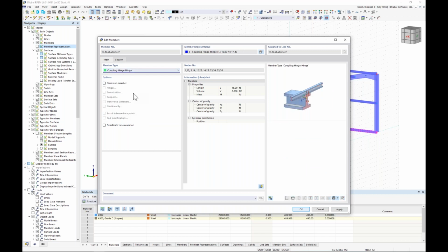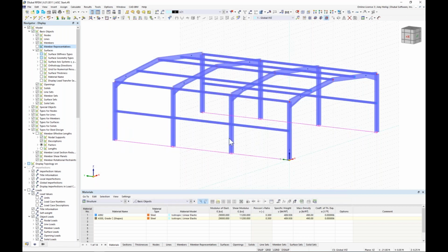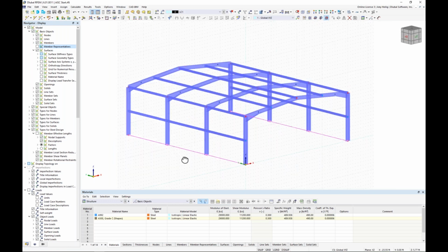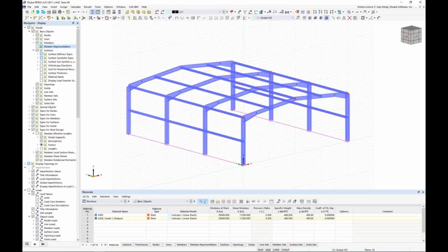So this is actually some type of rigid element here. The stiffness is very high. We don't need to specify a cross section, a material. All of that's handled internally with a very high stiffness, and a hinge is simply going to release the moment at either end. And the reason why I'm doing this is we will be defining surfaces along the facade walls for the entire structure, and I want all of the loads that are here at the lower part of the structure to be transferred back to the bottom of my columns and into those foundations. And we'll see that once we generate those surfaces.